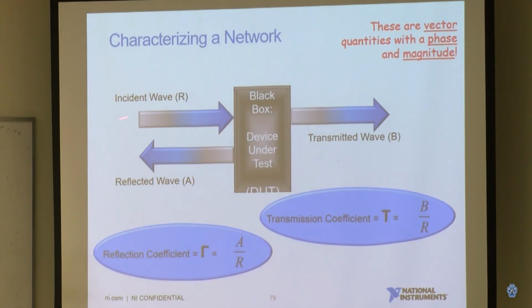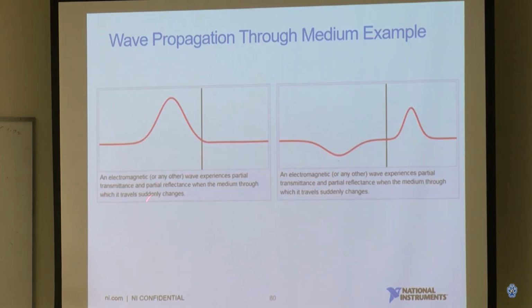So this comes back to the concept, the reflection coefficient. You have a signal going in to your device, and only a certain amount of the transmitted signal can go through, and some power reflects back. And you're using a VNA to measure those. So here's the idea, right? You have a sinusoid signal go through this impedance interface, and some of the signal goes back, and some signal goes out, but it degrades the amplitude.